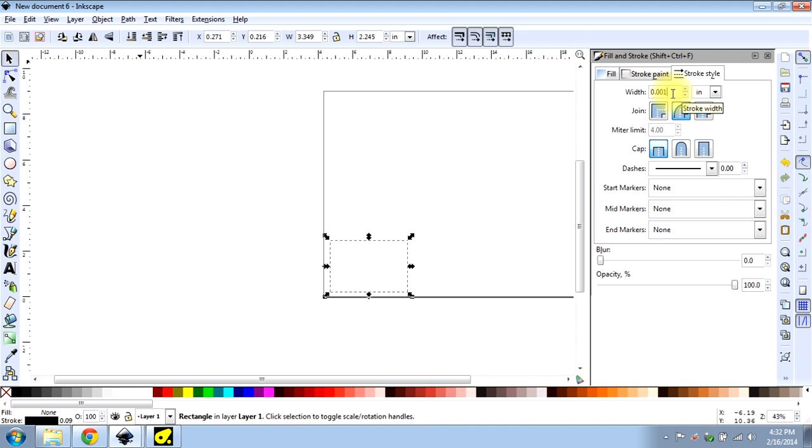You have to work with this line for the whole shebang. You can't work with thicker lines so you can see them and then convert at the end, because your dimensions are going to change. Only for the sake of this tutorial, I'm going to make bigger lines, just so you can see them on the screen grab. But again, I cannot stress enough, you have to work with 1,000th of an inch lines when you're drawing, so your dimensions stay straight. And when you export it, the cutting software knows literally what side of the line or the middle of the line you're talking about. When it's 1,000th, there's no confusion.